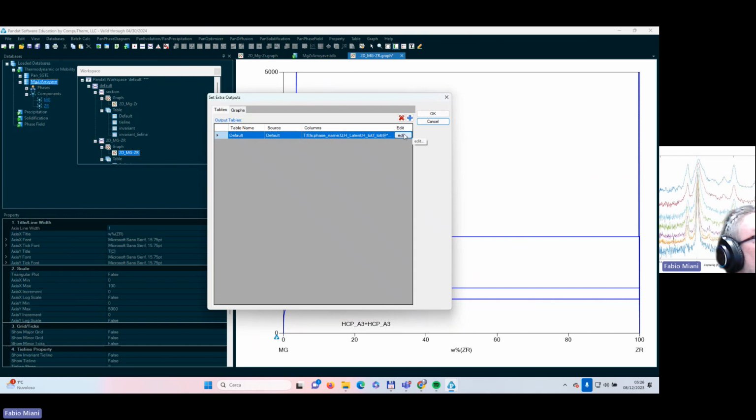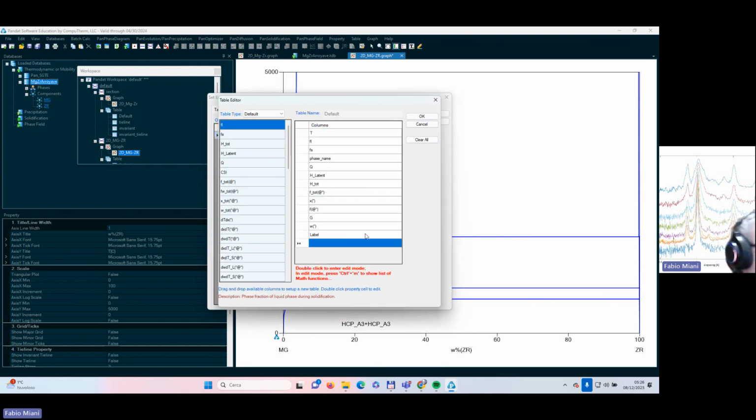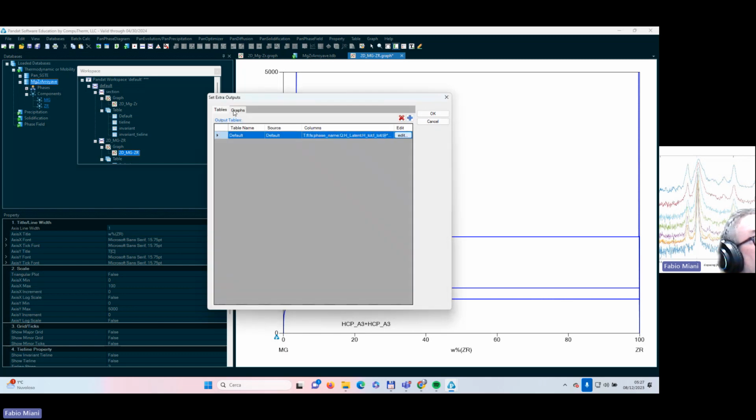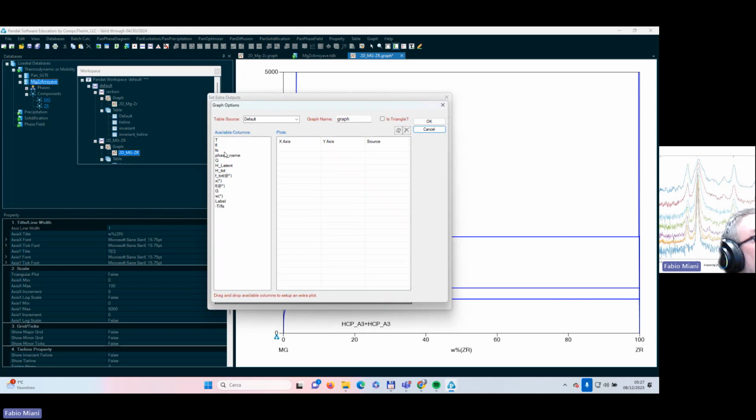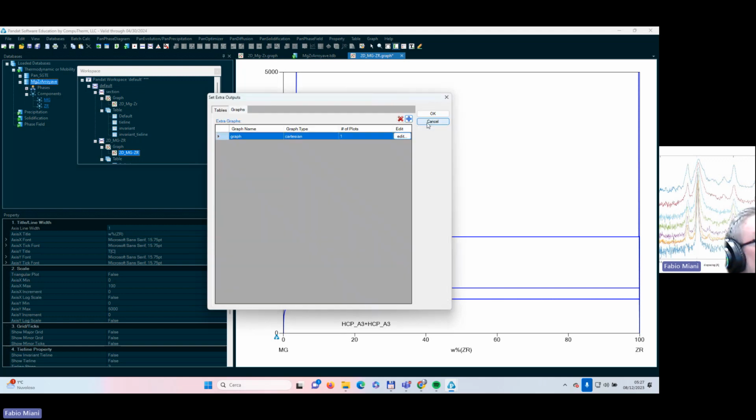So we want to add this function minus t, like we have done in lecture. So the derivative of the Scheil curve of temperature with the solid fraction, and then put the graph there like this one. So we put the phase fraction here and the derivative over there with the minus sign in order to keep it on the top and see what's going on.